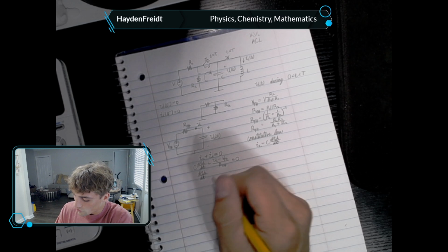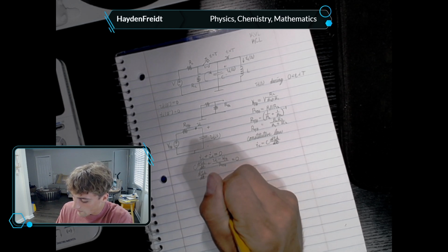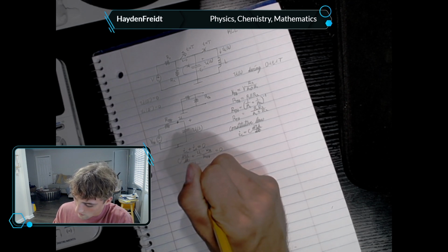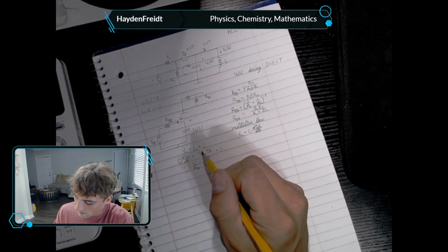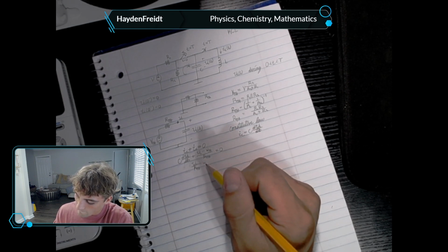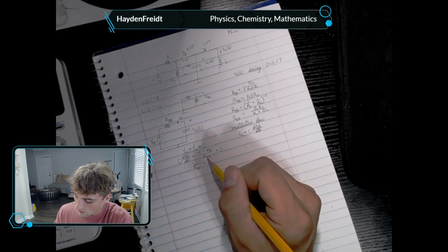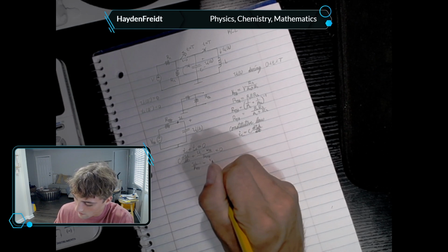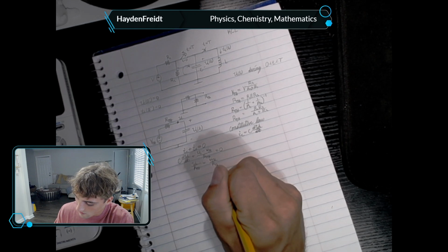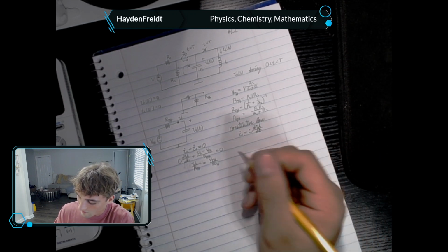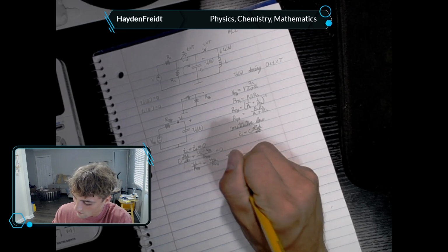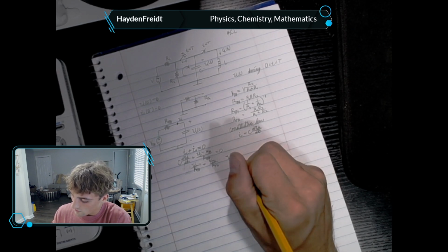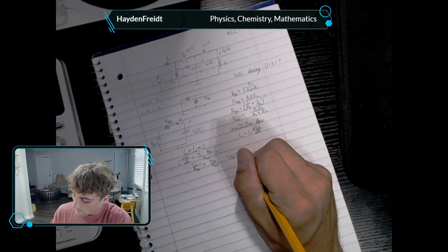So the derivative of the voltage across the capacitor with respect to time plus VC over RTH equals, if we separate this fraction into the numerator over this denominator minus this numerator over this denominator, and then we add VTH over RTH to the other side. VTH over RTH, that's just Thevenin. RTH is obviously going to cancel, and our particular solution, which we'll denote as VCP, the particular solution of the capacitor voltage, equals VTH.